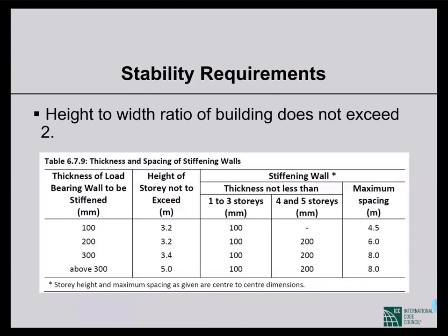Can we consider infill URM bearing wall in the FEA model to evaluate existing structure? First of all, infill URM is not considered as a bearing wall. They are non-load bearing walls. And infill URM can be considered in the FEA model by the equivalent strut model, or there are other models too, but the easiest one is the equivalent strut model.